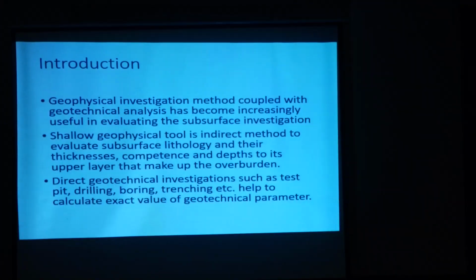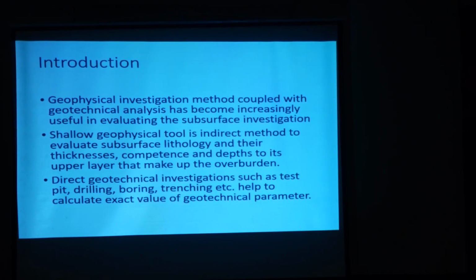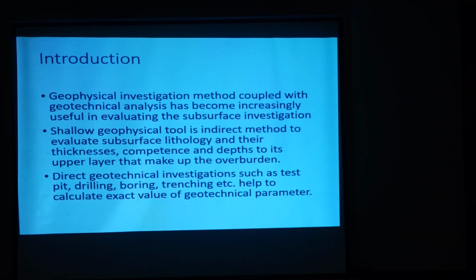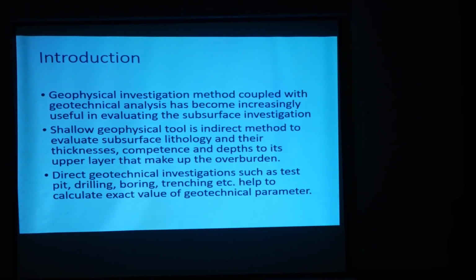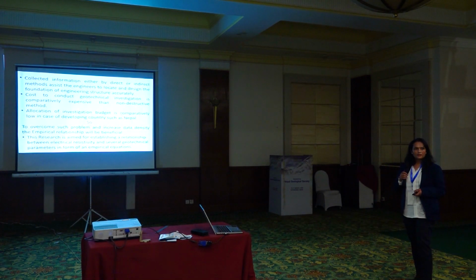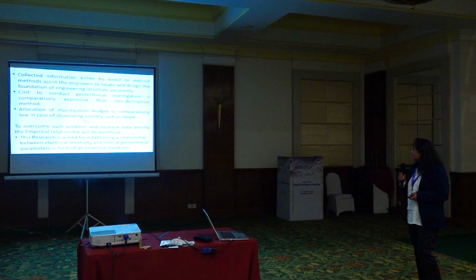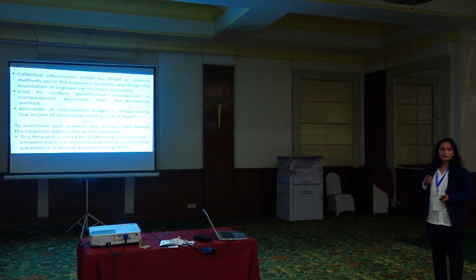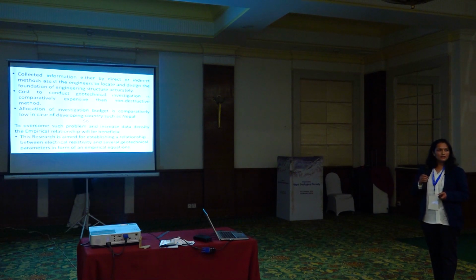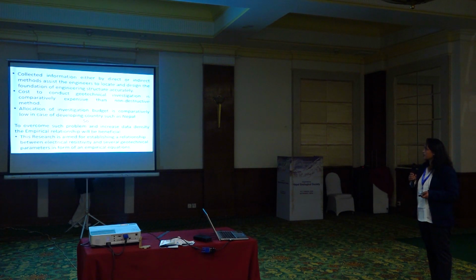Thank you very much. Geophysical tools are a direct method to evaluate surface lithology and its thickness, compactness, and depth, that is, the upper layer, meaning overburden. Collected information, by either direct or indirect methods, assists the engineer to locate and design the foundation of an engineering structure accurately. First, conducting a geotechnical investigation is comparatively more expensive than non-destructive methods.